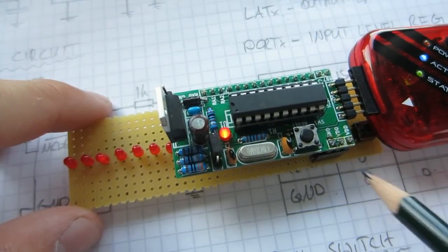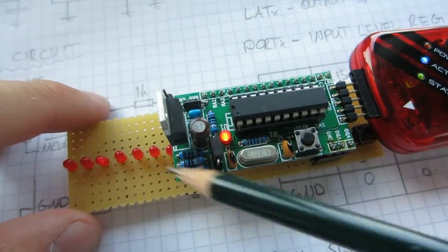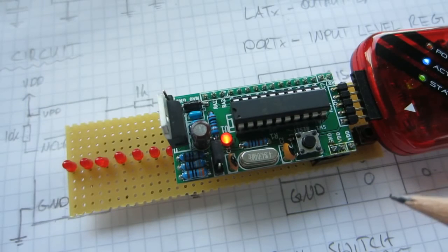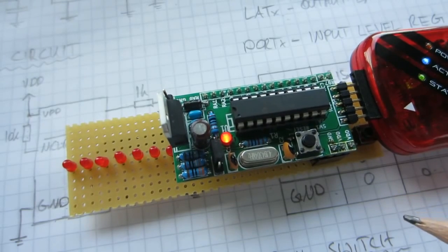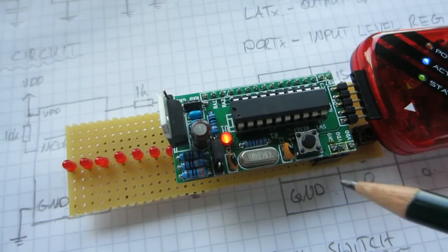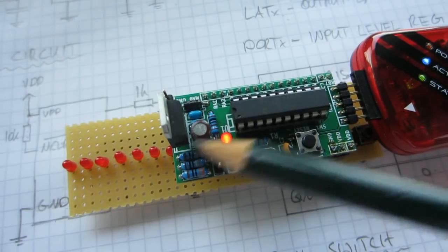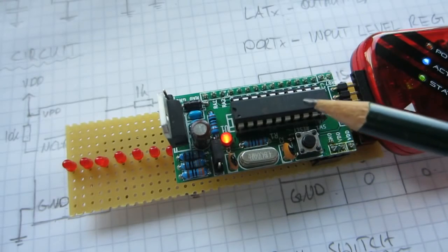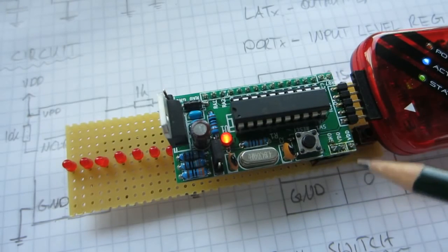Now note that I'm not using any debouncing here, because this is such a simple task that we don't need any debouncing, because we're not counting the number of button presses. It's not important how often a button is pressed. But if you want to navigate through a menu or have a user menu and want to count the number of button presses, then you would have to use debouncing. And of course this is just a simple task to demonstrate how to read an input and generate an output. Of course this is not a really useful task for a microcontroller, because you could just connect the LED to the switch if you want to switch it on.